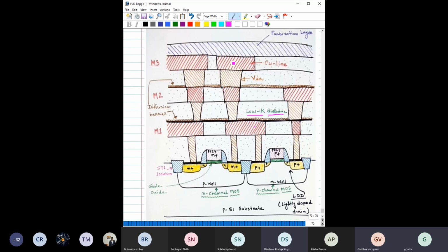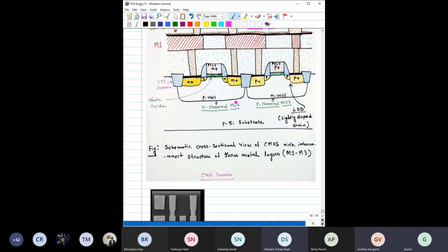Okay, so this is the whole overview of how the CMOS has been fabricated, and a brief discussion on how devices are isolated, and also what the different isolation techniques are, right? And why we have to shift from metal gate to polysilicon gate. Why polysilicon gate? Why can't we use metal gate for this self-aligned technique, right? All these things, from this discussion, you should have some clear view on that. So if you have any doubt, yeah.